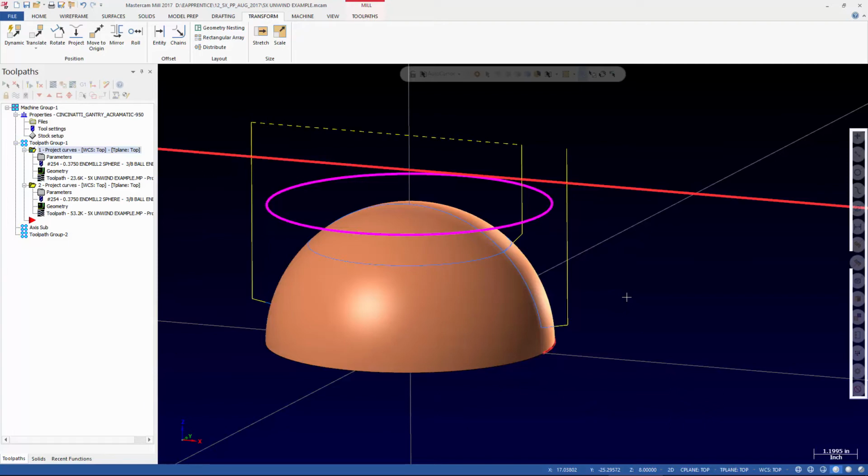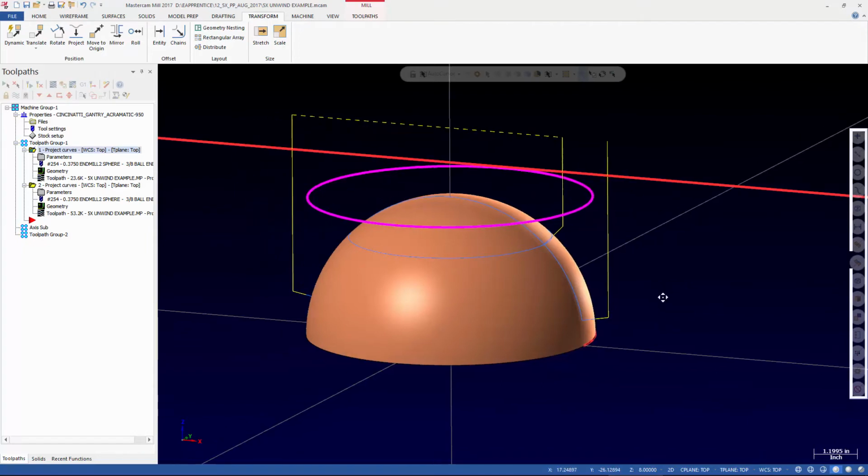Maybe you're doing aerospace and you've got pockets with tapered walls and undercut stuff, and you're doing it all day long. At that point, what's more cost effective? A solution that works 98% of the time? That 2% could be a spindle, and that's the problem. When you really need machine simulation, you really need good machine simulation that's accurate.